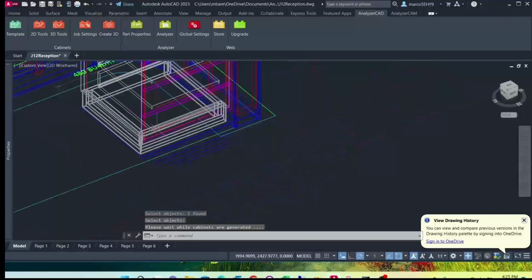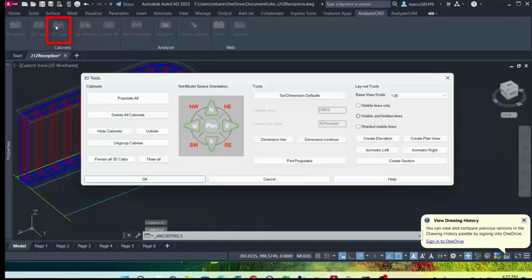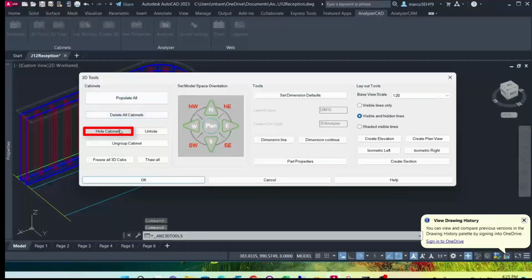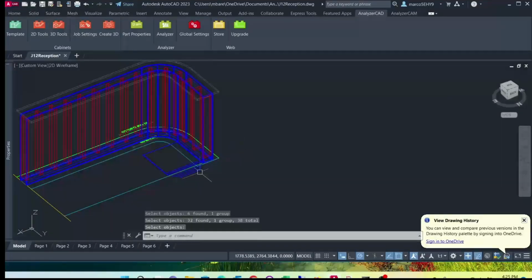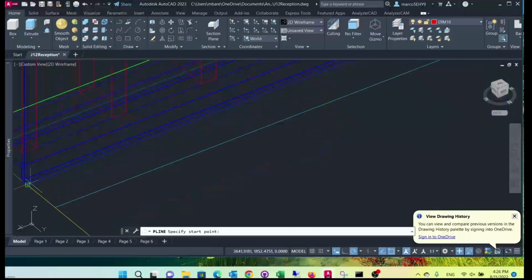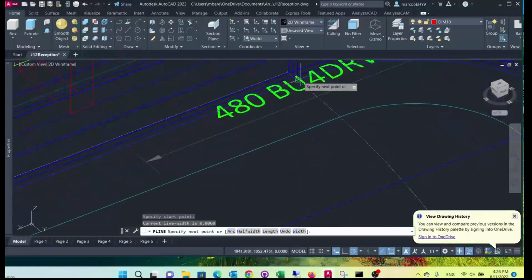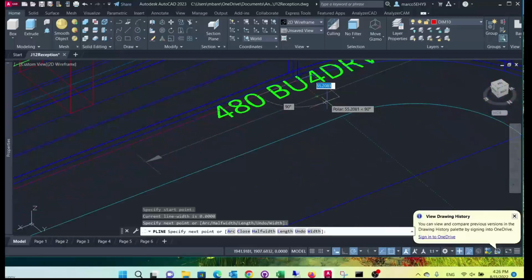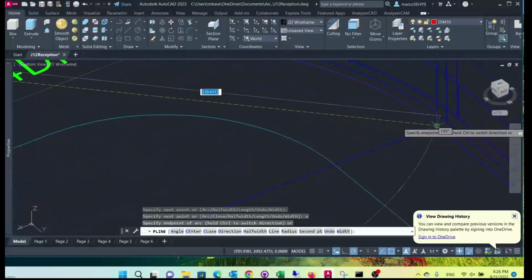The next part to draw is our benchtop. This is the actual desktop. Let's turn the cabinet layer off to make it easier to draw the desk. To draw the desktop, we are going to use a polyline. Then we basically follow the inside panel line. Change to arc, then back to a line again.